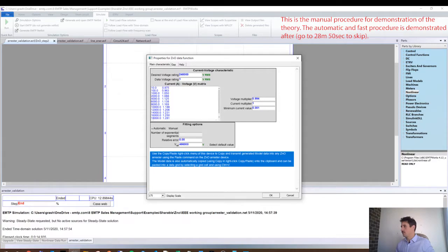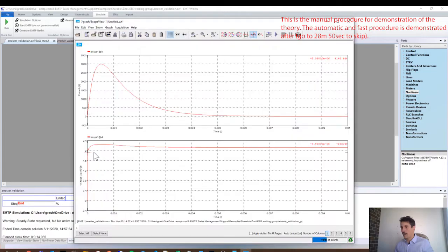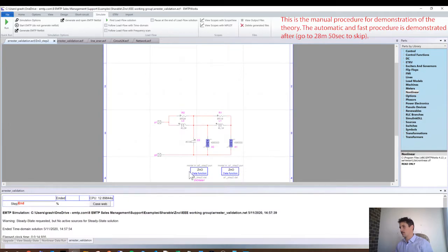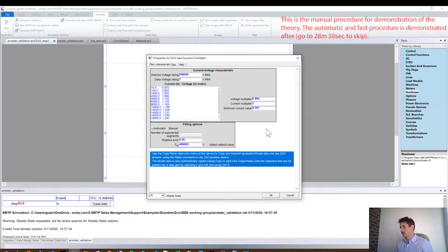If you put 1 here, by default it's 1, the voltage multiplier, you will have here something like 229. Then you do 229 divided by the value you want, 225. Then you take the inverse, and that's what you use for the multiplier, just to adjust the voltage.